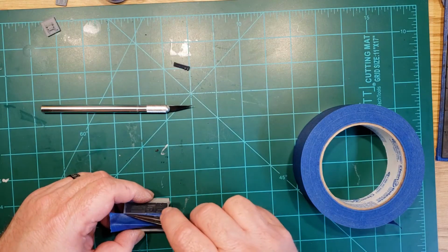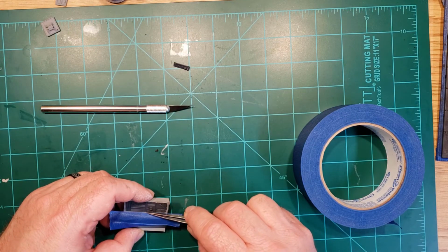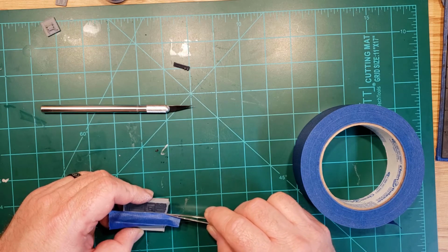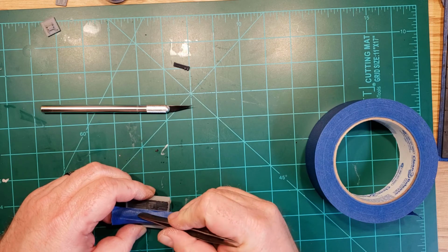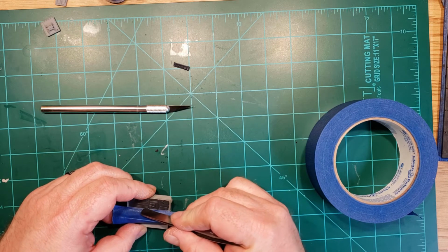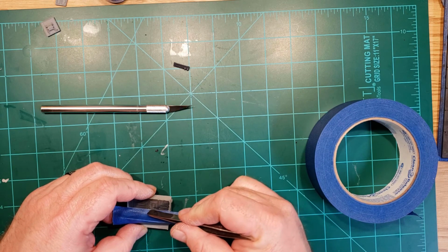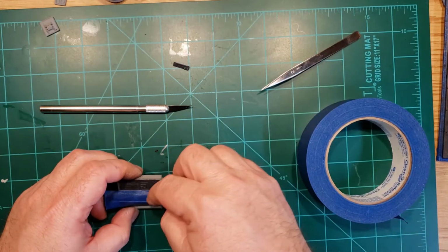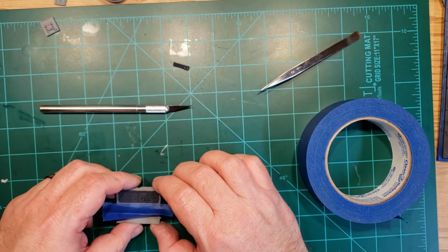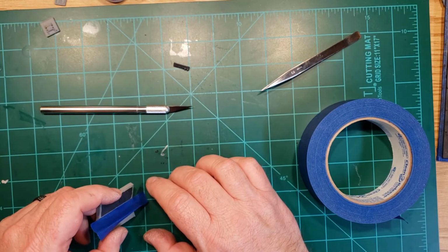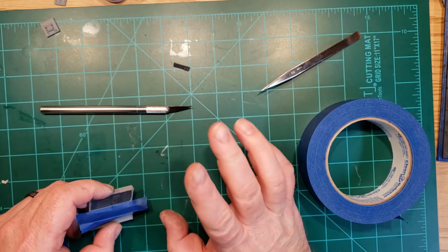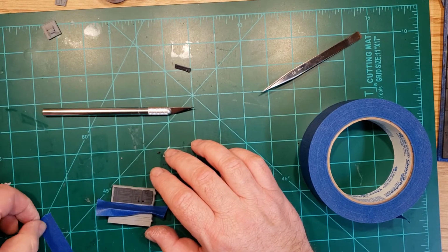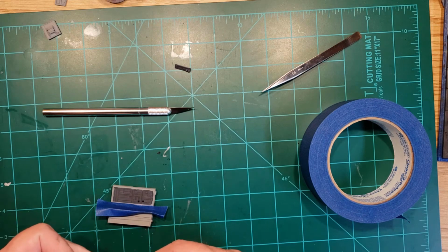So when you put down masking tape, it's a good idea to kind of what they call burnish it. So you burnish it down, and that's going to make sure that you get a good seam on it. So that way it helps so the paint doesn't bleed underneath. Okay, so we're going to have a little bit of bleedage there, but trust me, you guys will never know, except for the fact that I just told you.